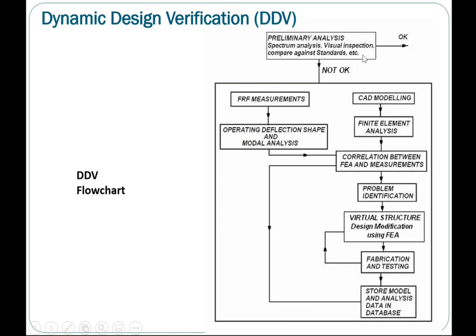So meaning these machines are all new, have no vibration issues, meaning we can say that you have no dynamic design issues. But those that exceeded the allowable limits, or are in zone C or D, these newly commissioned machines in zone C and D, basically it should indicate something is wrong with that particular machine, right?